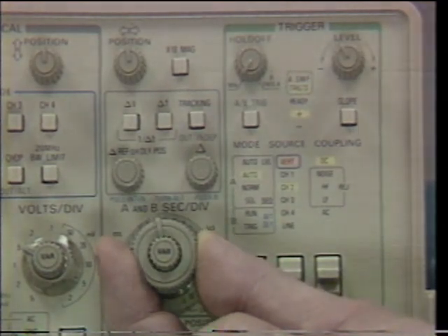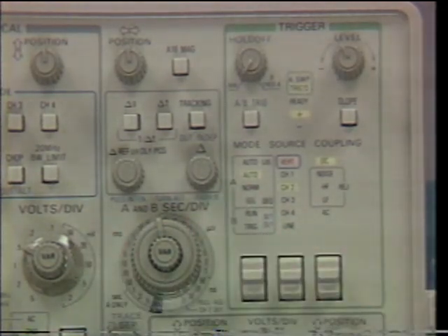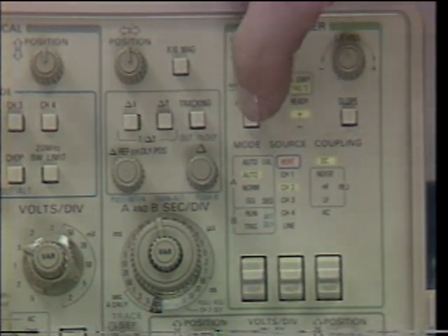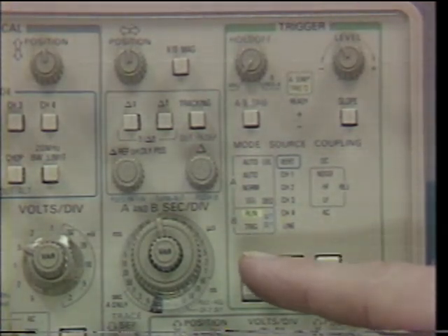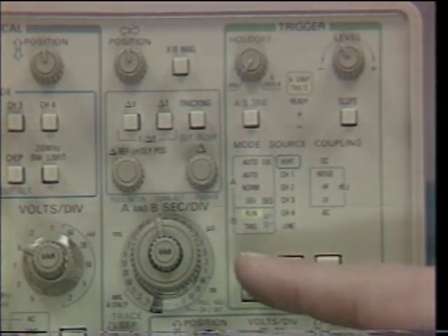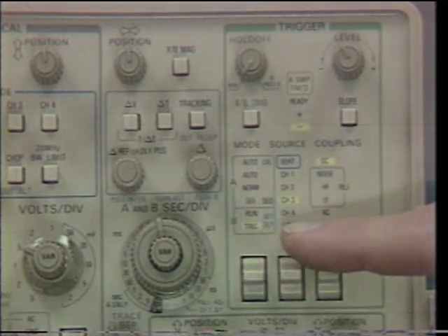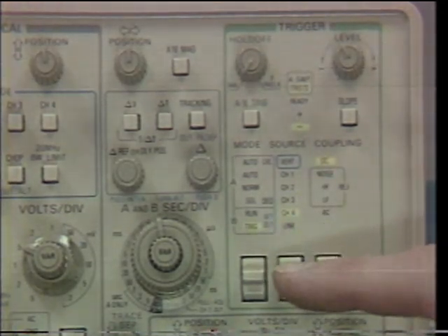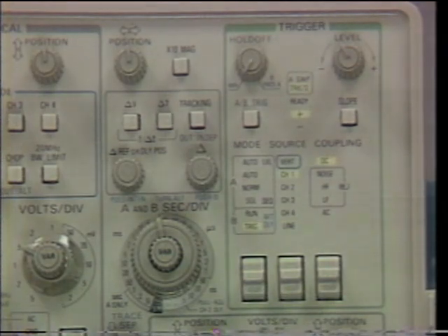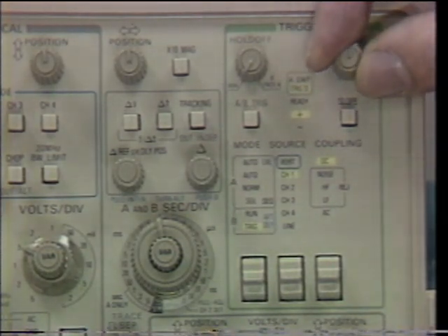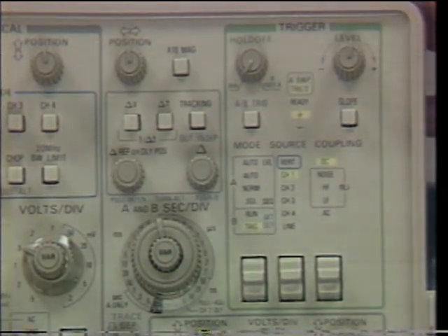When we operate the B sweep by pulling, unlocking the second per division knob, we then have the ability to select the B triggers by pushing the AB trig button, and we have one of two choices for the B trigger mode, either run after delay or triggerable after delay. As you can see, if we select triggerable after delay, we have the status of the source, coupling, and slope selections for the B trigger. In addition, we have independent control of the B trigger level, and the trigger level that was previously established for the A trigger is maintained even though we're changing this control.